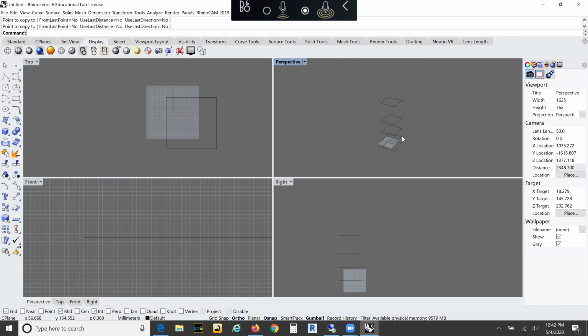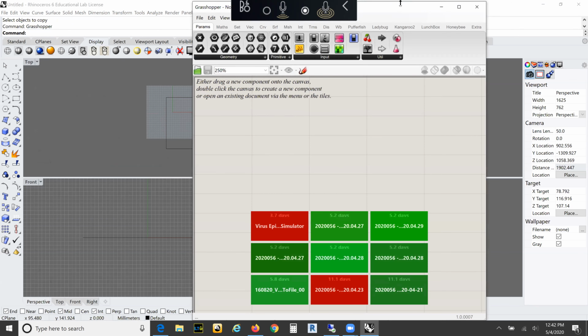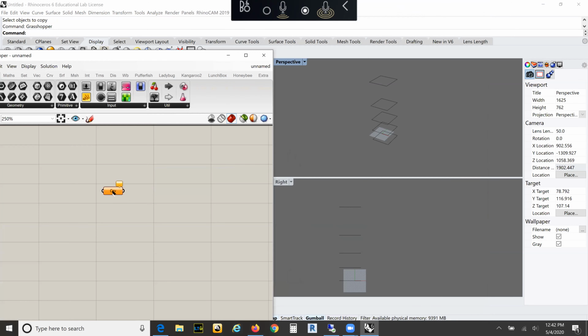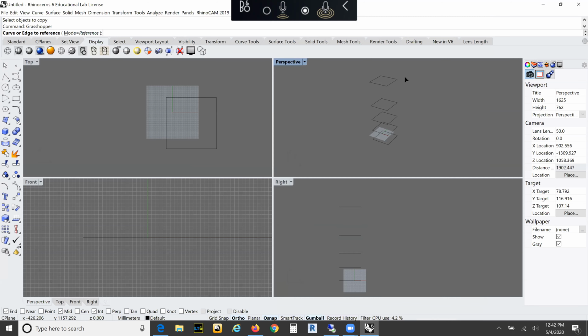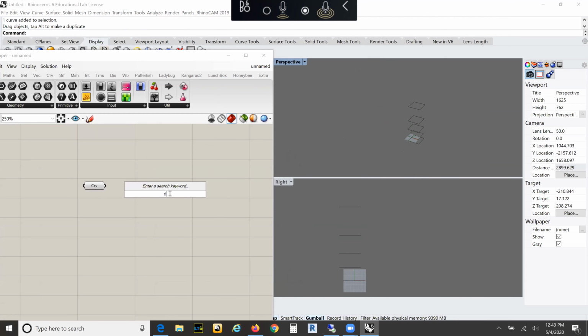All right, so let's just say we draw a couple profiles and a topper. And we can always grab our curve, set multiple curves. And this, for example, is just like how we subdivided our tower, or how we made our towers, just through a series of profiles. We can always then divide our curve.